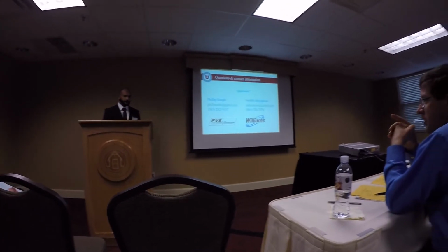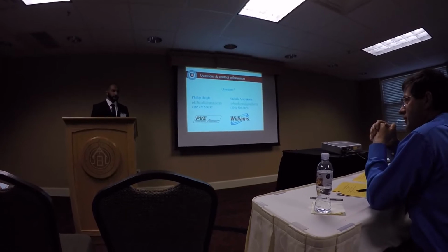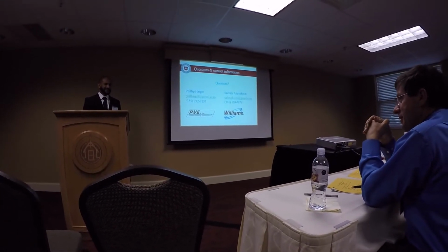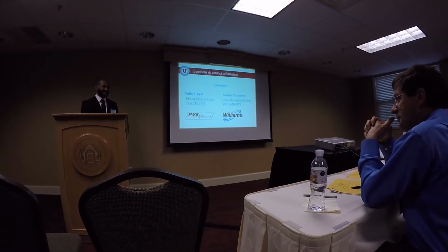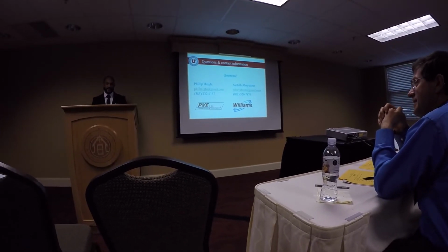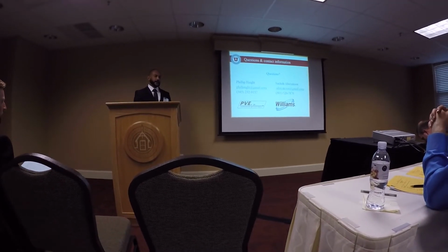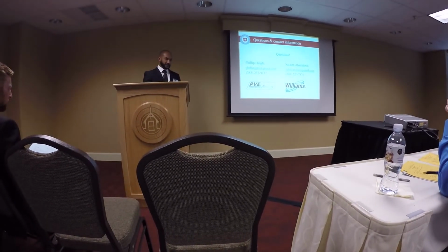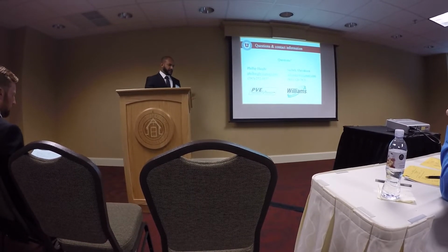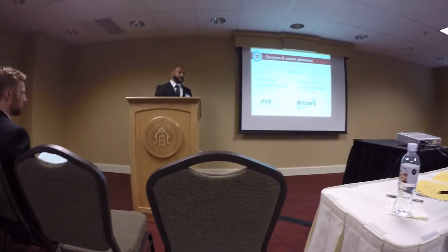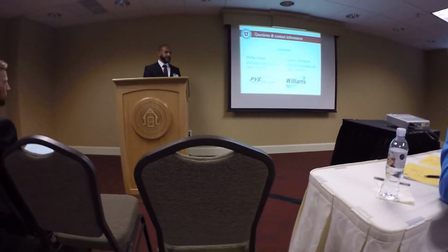In your list of codes, you did not mention NFPA 70E. Oh. And yet you did talk about arc flash. Do you want to talk a little bit about that? Yeah, I heavily used the NFPA 70 code book as well to do the calculations. When I was doing the calculations with SKM and trying to compare with NFPA 70E, I was not getting the same number that SKM was producing.